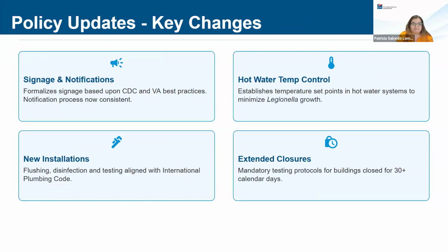Next slide, please. There's some key changes that we're going to highlight in the next couple of slides, including signage notifications. We have formalized our signage based on CDC and VA best practices, and notification process will now be consistent. We've also established water temperature set points in hot water systems to minimize Legionella growth.